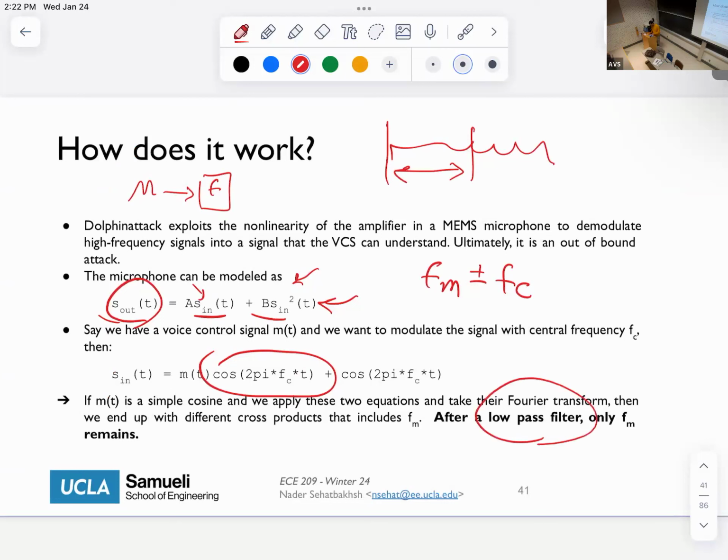So the low pass filtering is kind of the culprit here, unfortunately, that caused these things to move. And you need low pass filtering because you want to remove the noise. You don't want to send everything to the system, right? You want to low pass filter it so that you only send a specific range of frequency to the system. But an artifact of this is that since this is nonlinear and this is a low pass filter, you can sneak things into your system. That's kind of what happens. Okay.